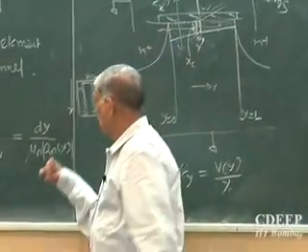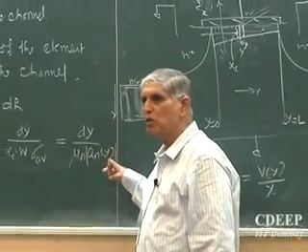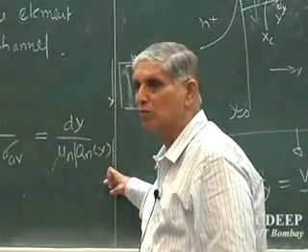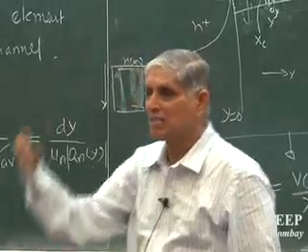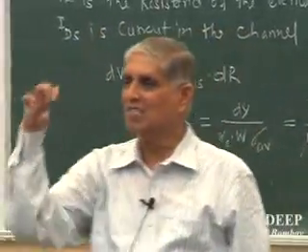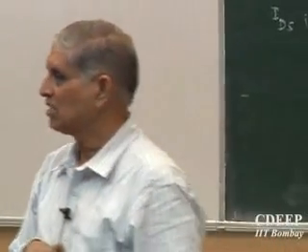Now, please remember, the inversion charge I can always calculate from where? The capacitor theory we have already done. At this element there is a MOS capacitor going on, and I know inversion charge is related to voltages. Which way? If I apply VGS, part of that will go to Vox, part will go to the semiconductor. No other charges are there, so whatever I put there will come to the semiconductor, opposite way. Now from the capacitor theory, we have already derived the expression for inversion charge.